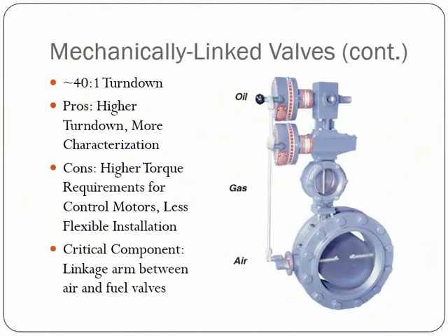So when you look at using these mechanically linked valves, you have to start planning and designing where your fuel train goes, where your combustion air blower goes, so that at some point between the gas train blower and the burner assembly, you have these lines all close enough to each other to be able to utilize mechanically linked valves.